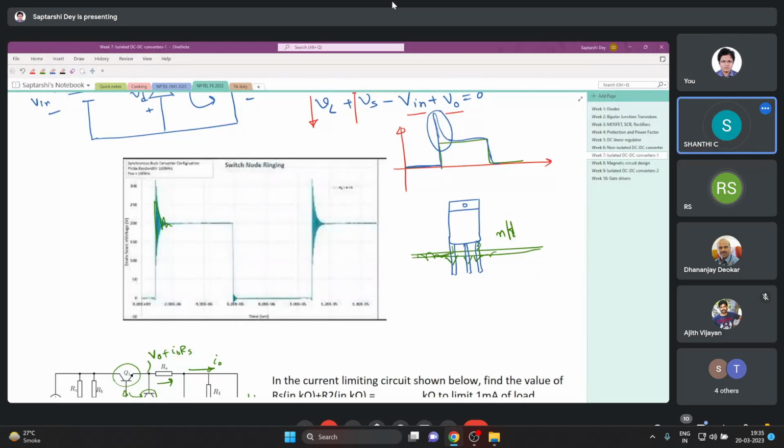First one. When the switch is on, the inductor current is rising. When the switch is off, the inductor is dissipating through this diode, sir. When it is closed, it is rising. When it is open, it is not dissipating. Is it an ideal diode? Yes, sir, all the components are ideal. Then it cannot dissipate, so it maintains a constant current.